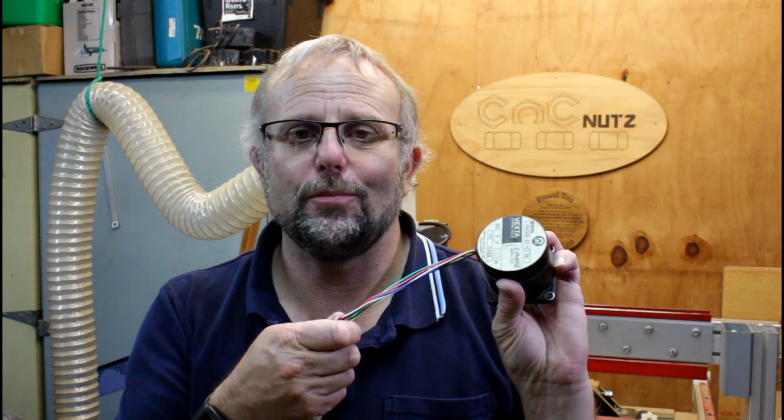So what has this got to do with anything? Well, let's look at our stepper motor. What is it? Well, basically it's an iron core with windings wrapped around it, just like my little electromagnet here, and just like my transformer is. It therefore has impedance to any AC signal, and these motors are driven by an AC signal. And if we want these motors to turn faster, we have to increase the frequency of that signal.